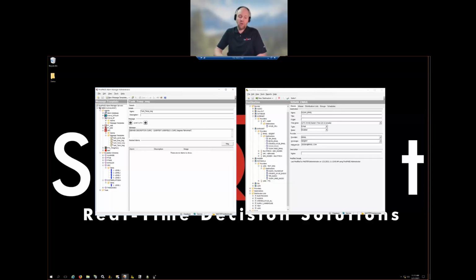And so our variable interface is opened up via the shift square bracket or the open curly brace, if you're familiar with that character. And I won't go through all of these variables, but I will focus in on user text. It relates to everything that's in that data source. And so user text would be different between OPC and system platform and any of the other data sources that we support. I'll go ahead and show you what the message templates look like from a system platform environment.